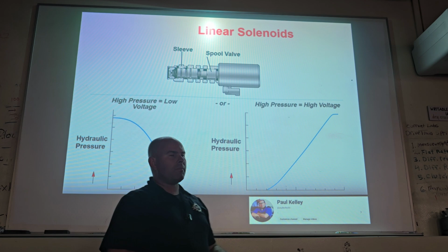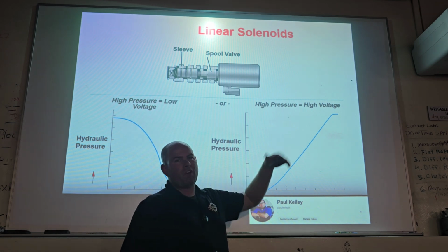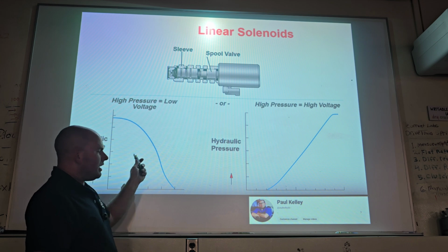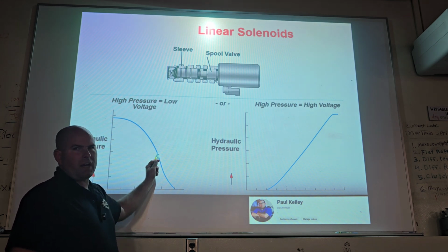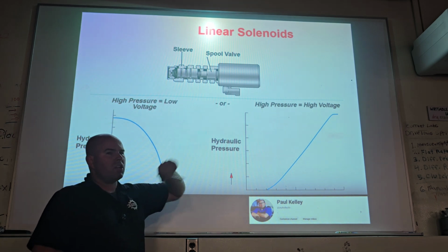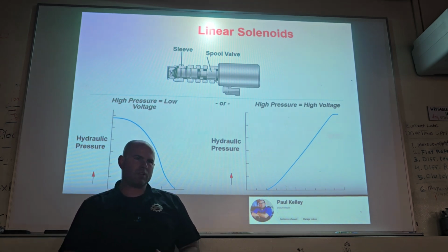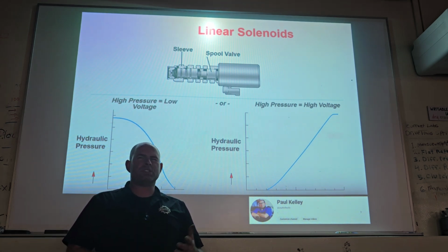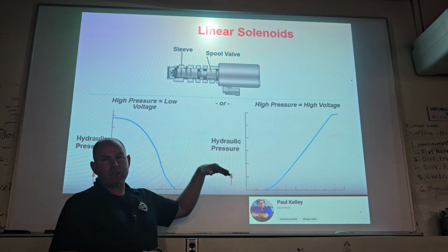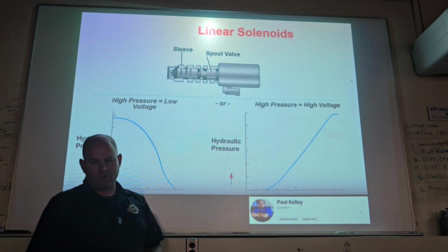Or if you put it in sport mode, it'll say, you know what, ramp it up fast, and you get a really firm shift. So these linear solenoids control not only shift timing, but also quality. When you have this type of solenoid, you have less of a need for those accumulators and things to really dampen it. We still tend to use accumulators, but we can also do a lot of that dampening through precise control of the solenoid, okay?